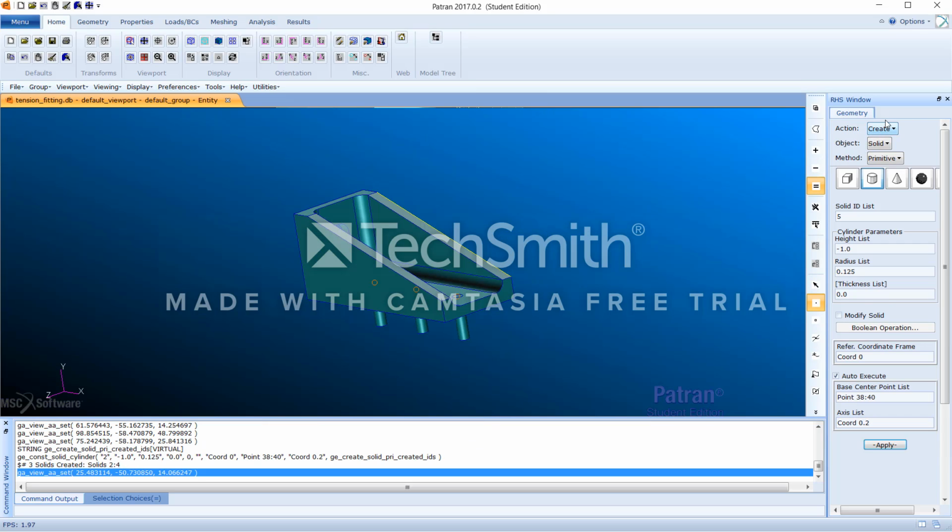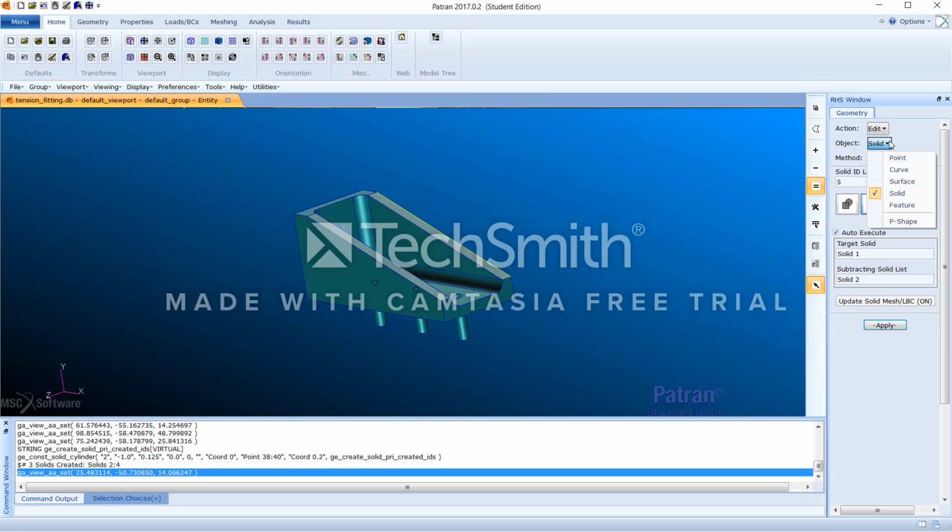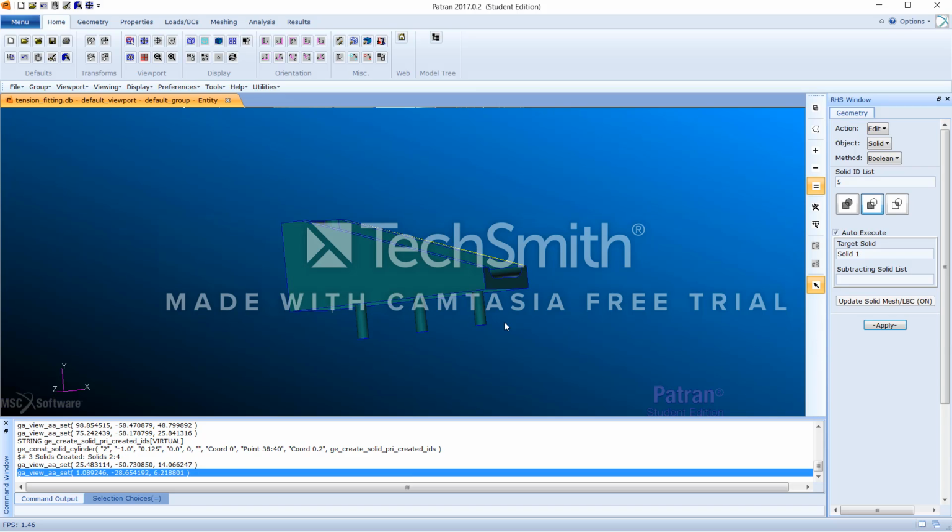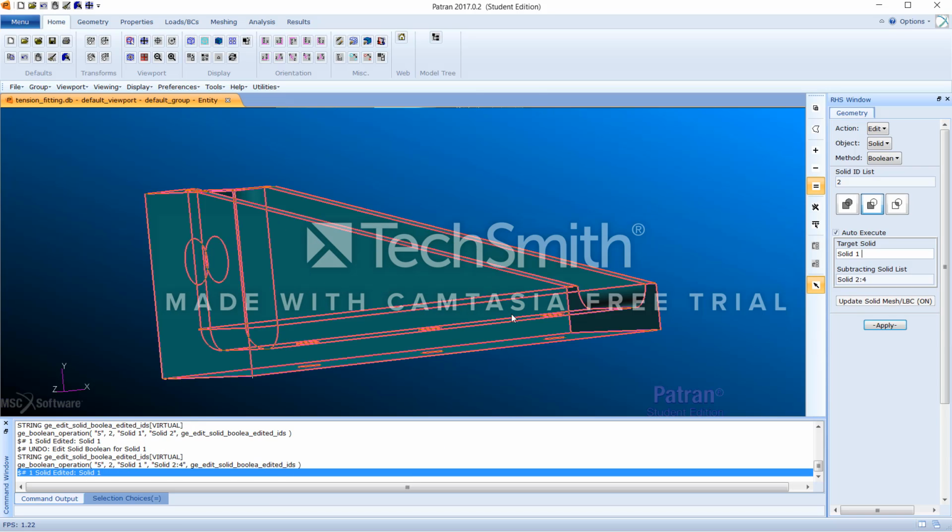To finish the holes, set action as edit, object as solid, and method as boolean. Select the subtract icon and select target solid as solid 1 and select the 3 cylinders for subtracting solid and apply it.